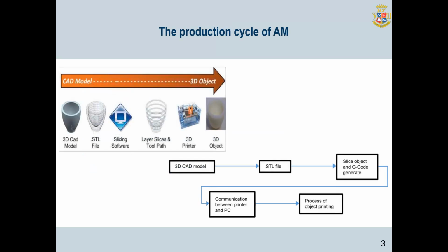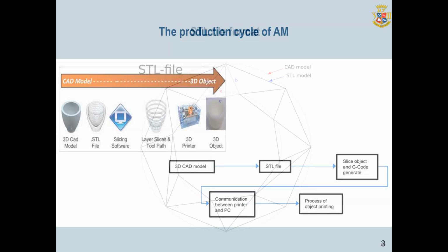The production cycle of additive manufacturing begins with the processing of a 3D digital model, which is divided into layers and oriented in the most appropriate way for printing. Slicing is a process of translating a 3D model into control code. If necessary, support structures are generated for printing overhanging elements. The issue of choosing the appropriate slicing software with settings to ensure the quality of the printing process, taking into account time and material constraints, is relevant.